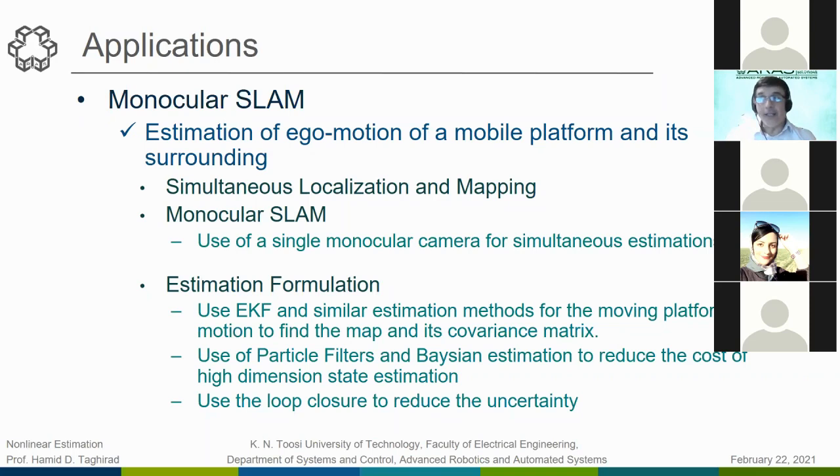But again, the infrastructure is there, and now we have two systems: the motion model of the robot and also the observation model that we get from the camera. These two can be put together, and when you move, you have different states, and you get an augmented state for your Kalman filter or your nonlinear observer to estimate it.